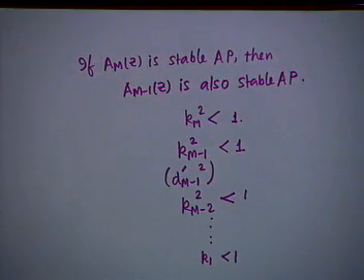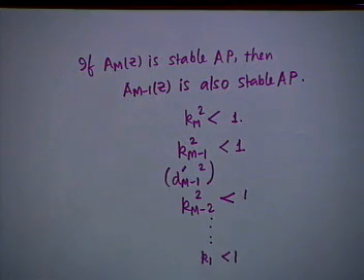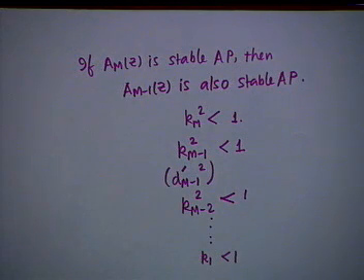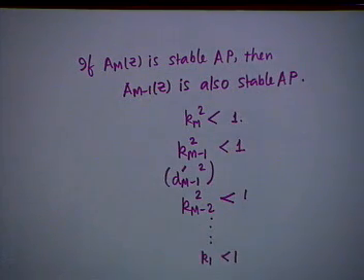It is one of the most beautiful theorems in DSP, which shows how to avoid all these root finding. It is a little bit of exercise, but that recursion relation, you see, you do not have to find all the transfer functions. All you have to find are the polynomials, the denominator polynomial. And denominator polynomial means you have to find the coefficients of the polynomials, and therefore that relationship di prime relating to di is the only one that you shall use in the process. Okay? And what you will do is you will find Km minus 1 up to K1.